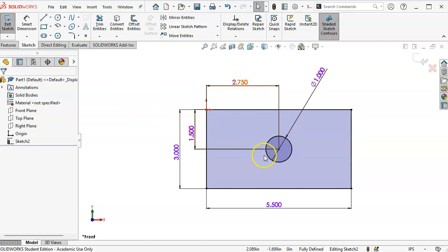So I could measure from the inside of the hole to the edge with my calipers, know the diameter, put that dimension in as a measured value, and then change it to the center and say, oh, that's a nice fractional or nice whole metric number, and it kind of verifies and double checks your process.